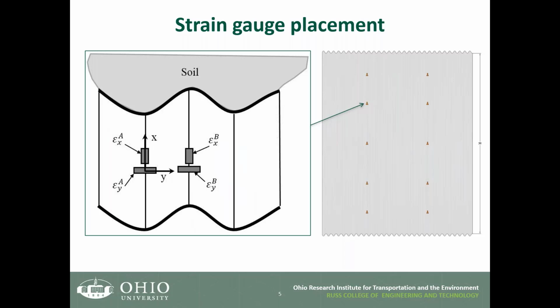One thing I want to point out is that culverts, when they are corrugated pipe, are completely different from any other structure that we design in the infrastructure. Why are they different? The reason is because the soil is applying the load, but the soil is also providing the resistance. So you could see when the soil goes inside of the corrugation, you get a good amount of lateral support.